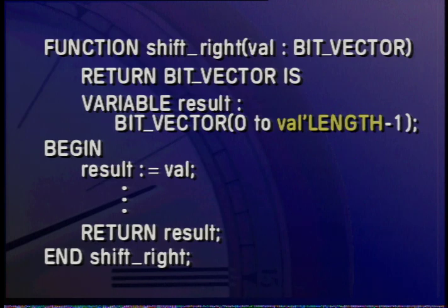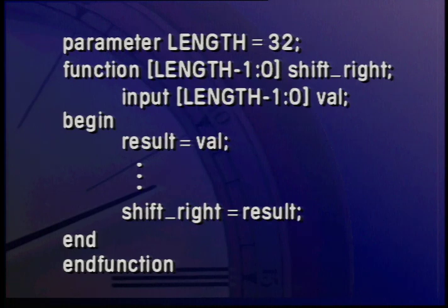If you do this in VHDL, you only need one description for any width of shifter. The width is determined at simulation time. So if your model has a 2-bit shifter and a 64-bit shifter, there is only one piece of code which represents them both. In Verilog, though, while you still have only one piece of source code, the width is determined by a compile time parameter. Thus, the 2-bit shifter would result in one module at simulation time, and the 64-bit shifter would result in a different one. Each of these would be faster than a more general module which could handle both widths.